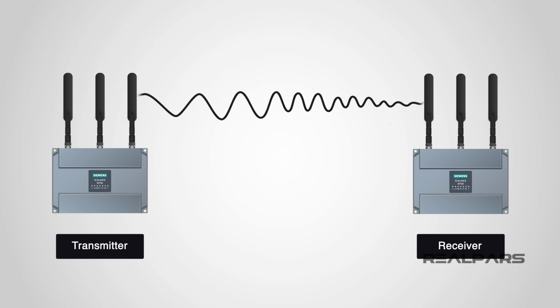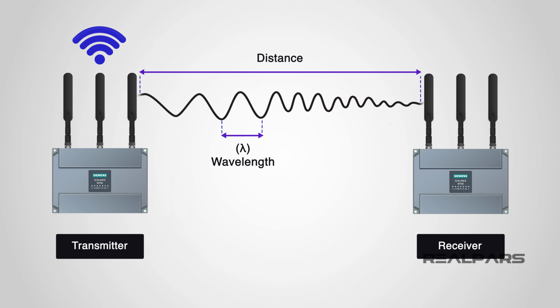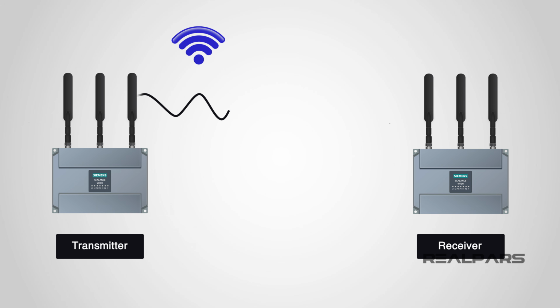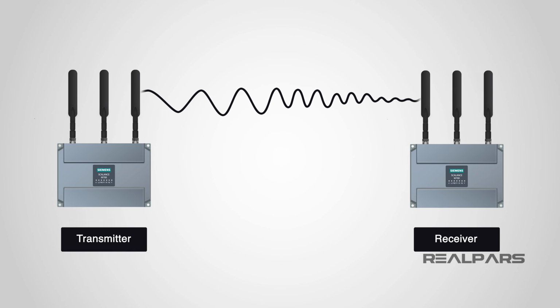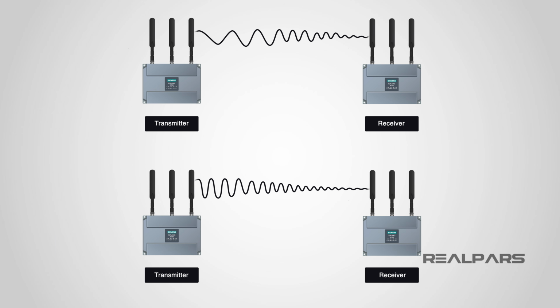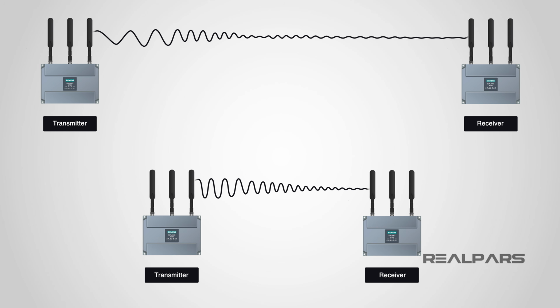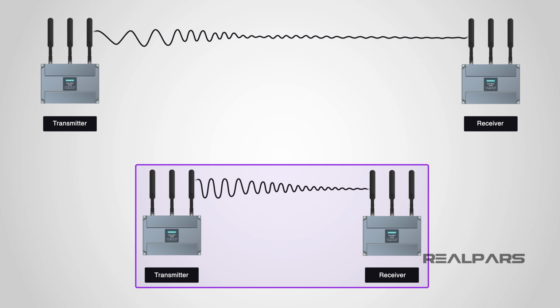There are several parameters involved with attenuation. They are distance, wavelength, and the transmit power. As we now know, the power of the signal reduces as the signal propagates. And so, just to let you know, the shorter waves, or higher frequency waves, will experience higher attenuation. Path loss, or L, depends on distance and wavelength. The greater the distance means lower power to be received, and with the wavelength, attenuation is greater for shorter wavelengths.